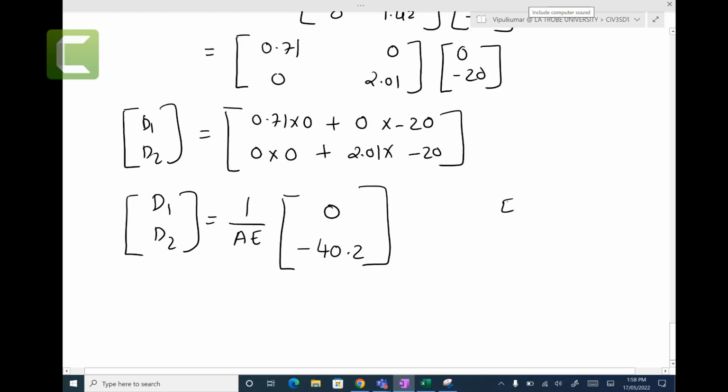All right, so we're going to plug in the values of AE, and the E is given in the form of E equal to 200 gigapascals. So what we are working with is length in meters and load in kilonewtons. Do you understand that, right? So far in the matrix, we are taking length in meters and load in kilonewtons. So we need this in kilonewtons and meters. Do you agree with me?